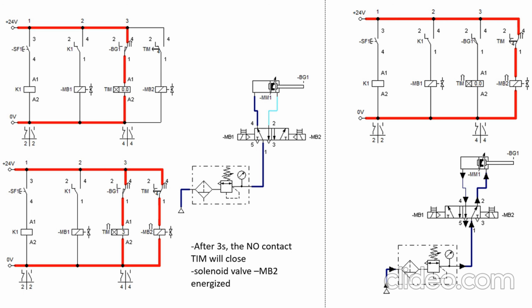So after 3 seconds, the normally open contact will close, and then the solenoid valve MB2 will be energized.